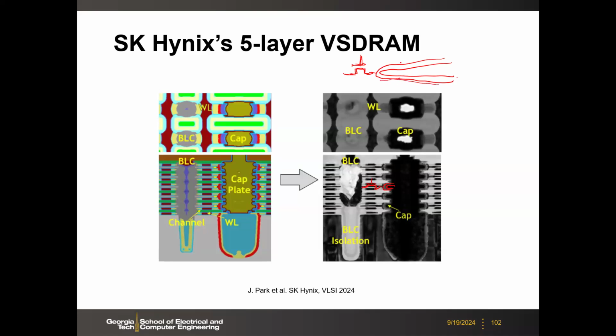For example, for a 12 nanometer node, 100 means this cap is above 1 micrometer long, right? So if we keep this 1 micrometer long cap horizontally, that takes a lot of space, actually, right? Previously, you are doing 1T, 1C, okay. And then this is only like 12 nanometer or something like that. Or let's say 20 nanometer, less than 20.